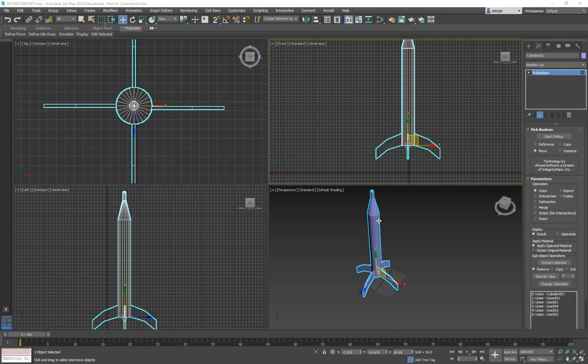A kinematic rigid body is one where, regardless of its own mass or other forces, you simply define the motion only. It simulates the motion of an actual solid model, but its weight, mass, and other forces are not actually computed.